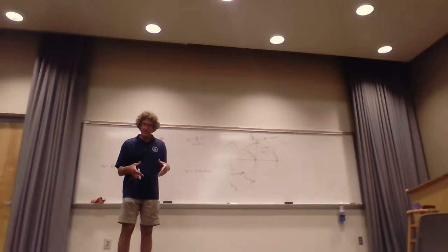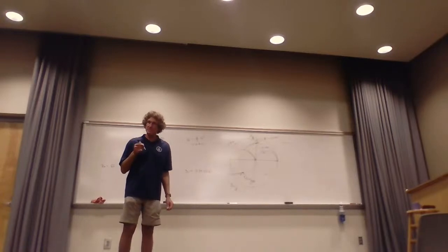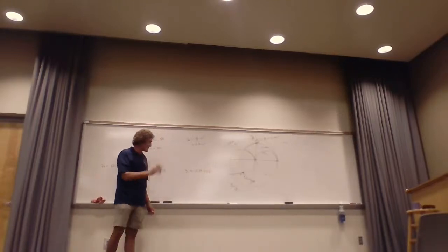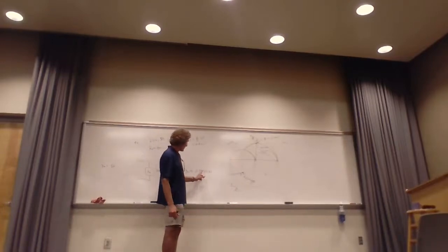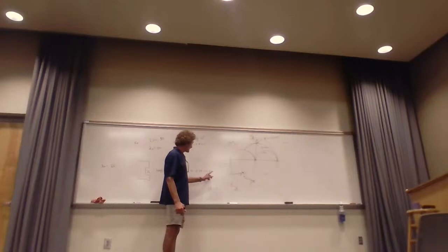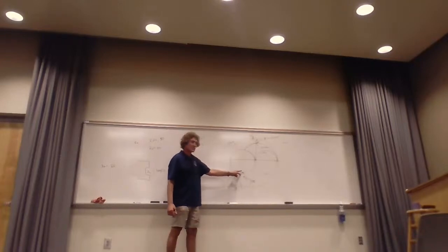But if you have a rotated Smith chart, you can do this very easily, as long as you have a sharp pencil to plot these points. What can you give me? It's 0.34 for sure, and it's J something, because we got to get the difference in J values. This is minus J 0.86, and we're going to get here, so it's minus J point like 0.6, something like that.